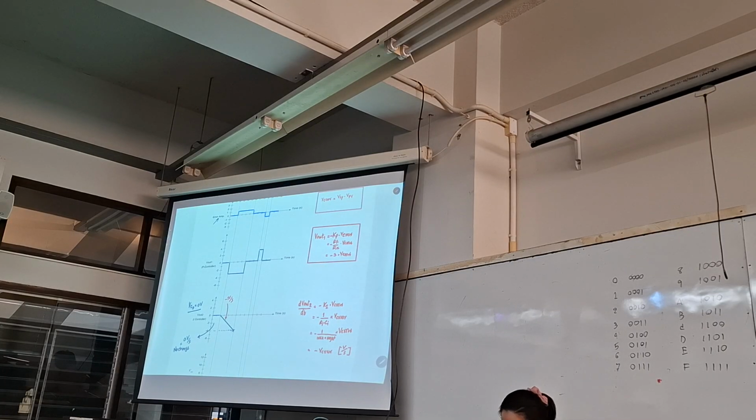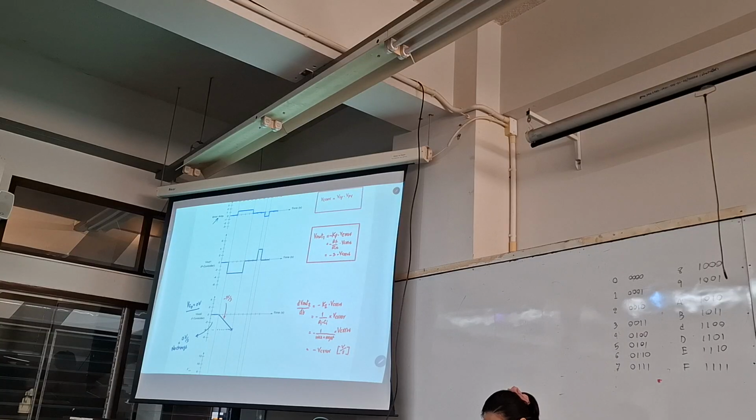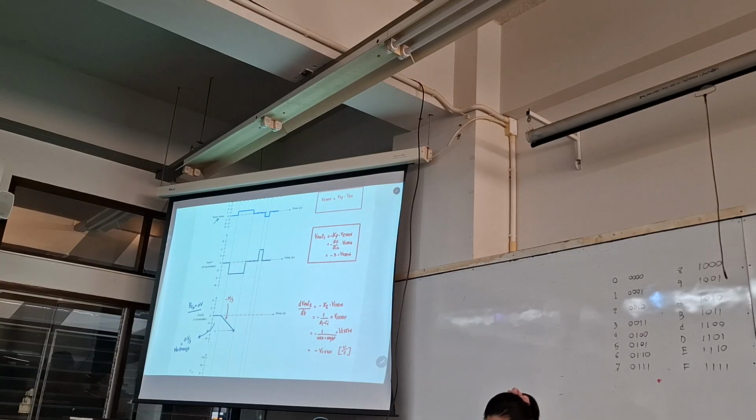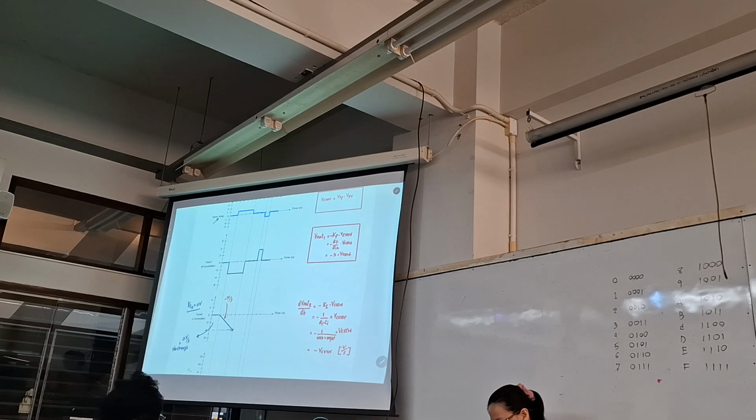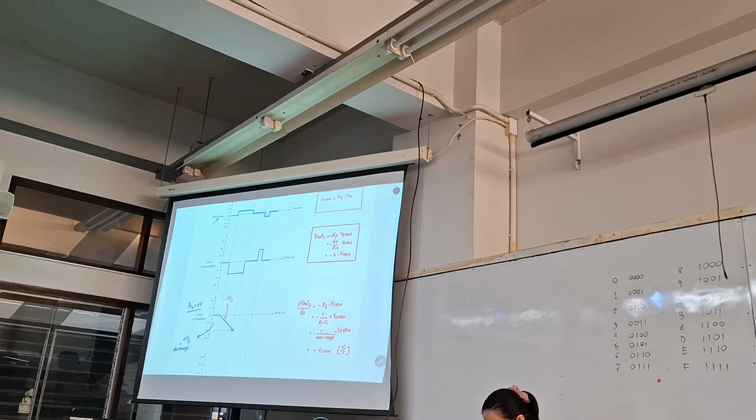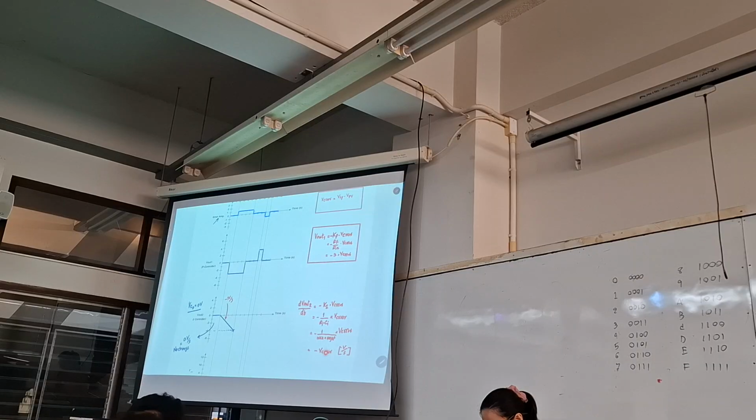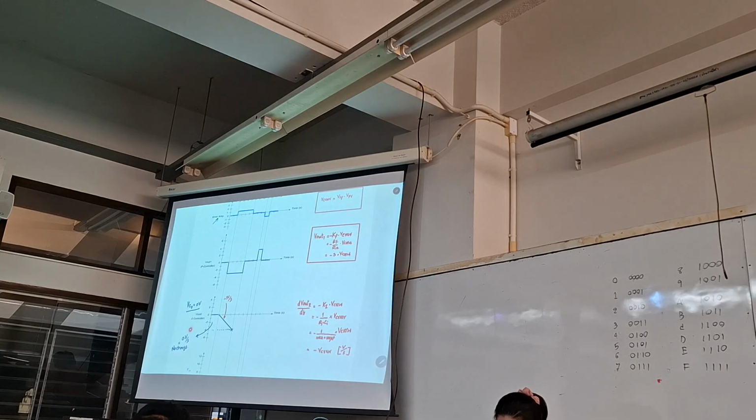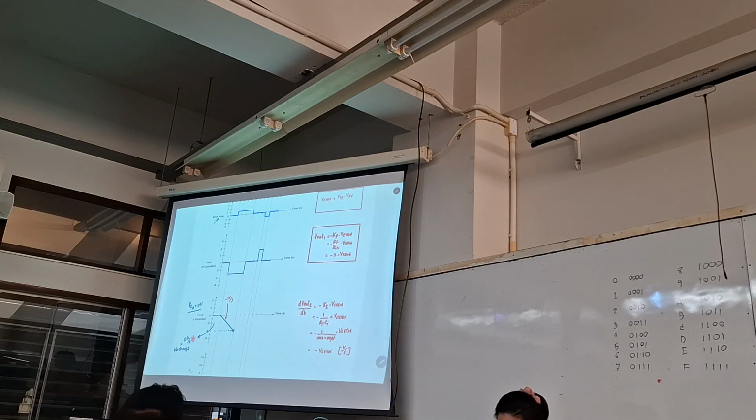Okay, let's continue to the next interval. Again we have 0 here. So substitute 0 in the equations, then you have 0 volt per second. What is the meaning of 0 volt per second? It doesn't mean 0 volt, but it will give no change anymore at the output.